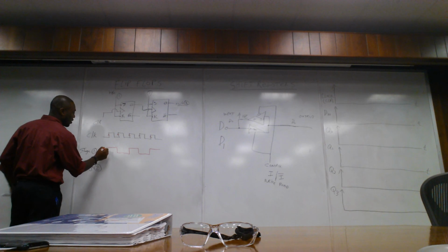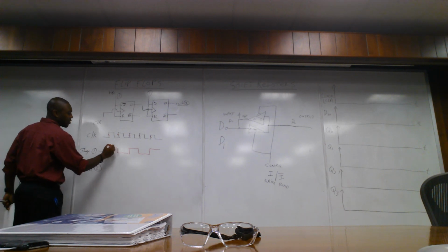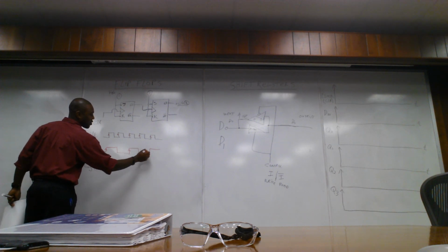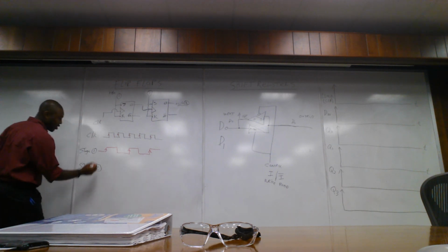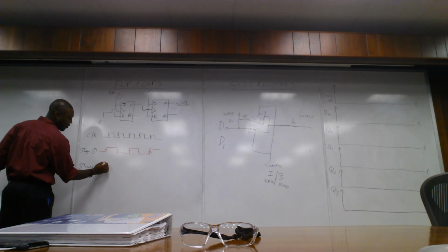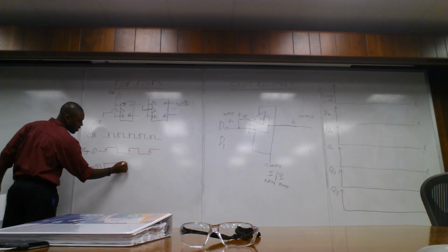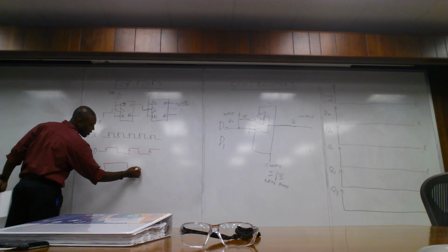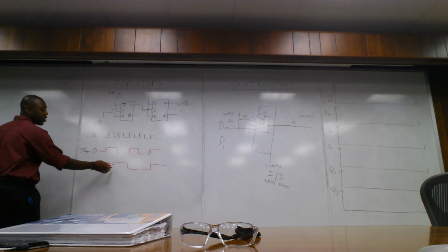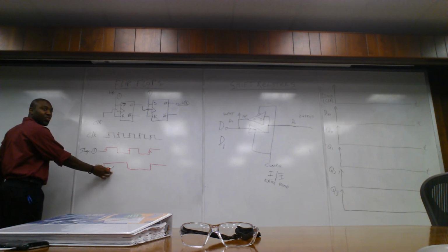So now this goes up on the rising edge. Goes down. This is your rising edge. Go down, this is your rising edge. So now your stage 2 is saying, okay, let's go up. We go across, we're going to do nothing until we go down. We're going to do nothing again until it goes up and continue. So now this divides by 2 also.